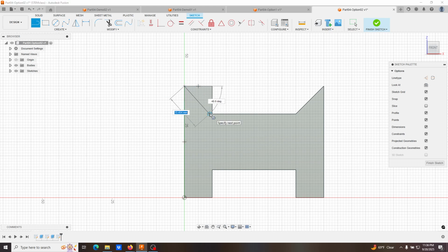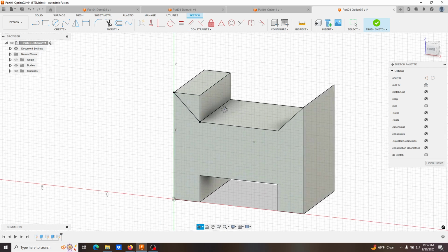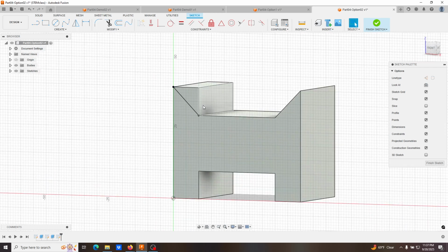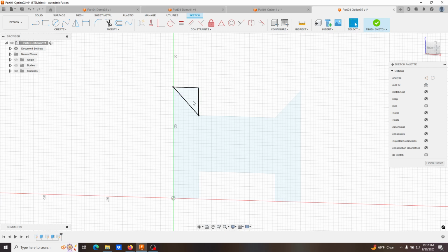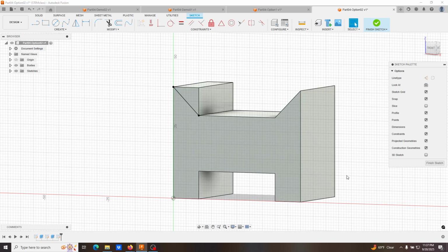Now, just to highlight what I was saying earlier, one thing that Fusion does that makes me kind of nervous is that generally anytime I want to do a cut or an extrusion, I want a closed feature. But Fusion will take in context the parallel faces you have. So if I hide my bodies again, this is my only line here, but you'll see how it highlights here. This just makes me nervous because of my experience with other CAD programs.